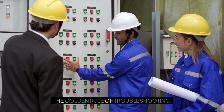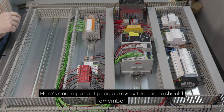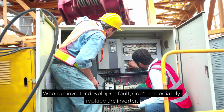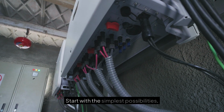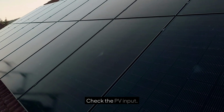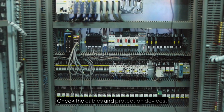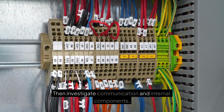The golden rule of troubleshooting. Here's one important principle every technician should remember. Don't troubleshoot by guessing, troubleshoot by measuring. When an inverter develops a fault, don't immediately replace the inverter. Start with the simplest possibilities. Check the fault code. Check the battery. Check the PV input. Check the AC supply. Check the cables and protection devices. Then investigate communication and internal components.